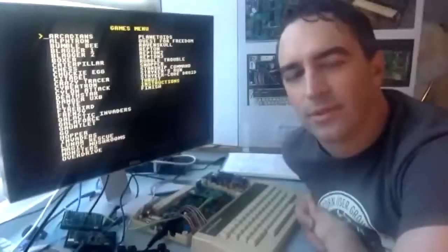I've ported all of BeebFPGA to Verilog so that I could run it on the IceStorm stuff. And once you get into the swing of it, it actually doesn't take that long. There's a VHDL to Verilog translator that gets you about 70% of the way there. So it's probably a day's work to convert Electron FPGA to Verilog.